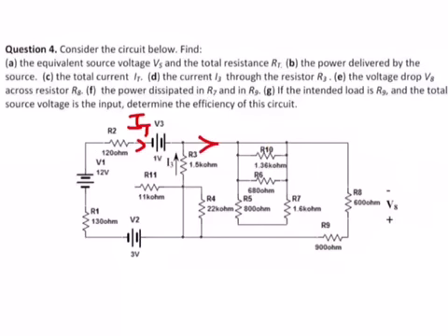Then what is going to happen, because current will go through the least resistive path, it will go through the short circuit. And it will completely ignore this parallel combination. So all these resistances can be ignored. And this means there is no current flowing in R7. This means that the power dissipated in R7 is 0. I don't have to worry about it even.